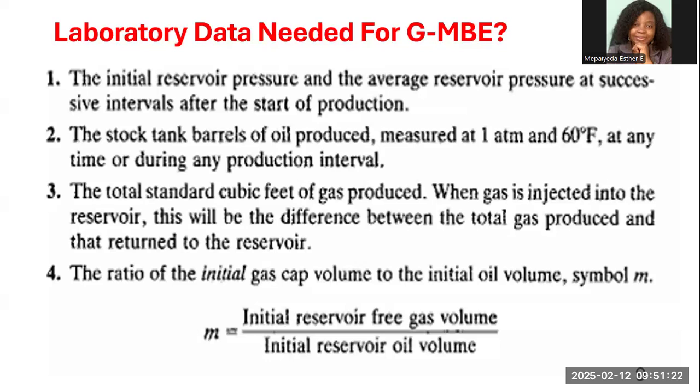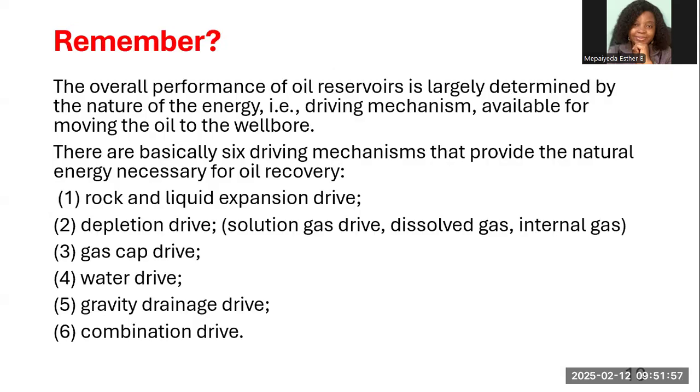While if the gas is driven off from the oil, that is, the gas is removed from the oil as pressure drops, that's differential separation. So you can check your text to know the difference between flash separation and differential separation, which are carried out in the laboratory in order to obtain your solution gas oil ratio data and other PVT data that are equally needed in the development of your MBE, material balance equation.